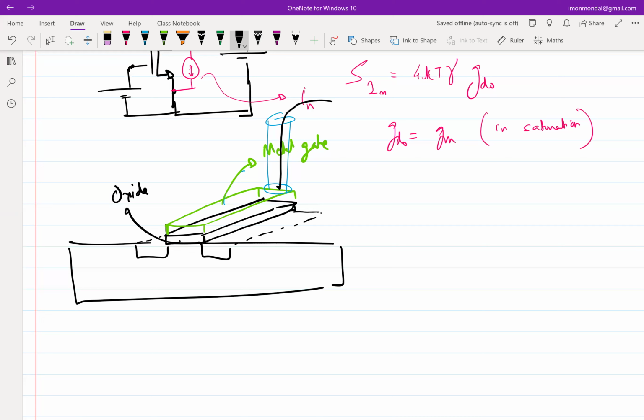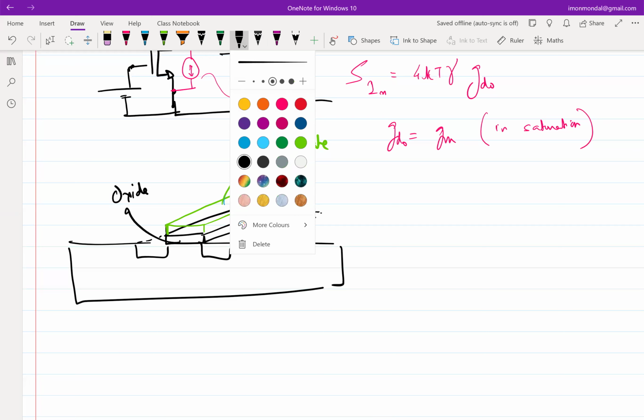You can think of this as a capacitor where the signal is coming on one side of the capacitor plate, but it has to also reach the other side of the plate. It's not a problem if the resistivity is 0, it's instantaneous. But the resistivity is never 0. It will have some finite value.